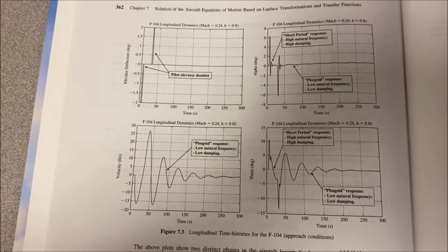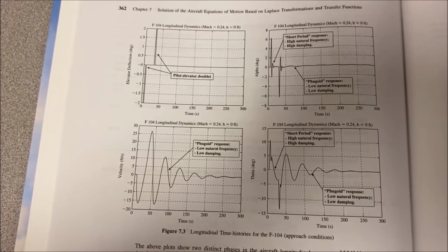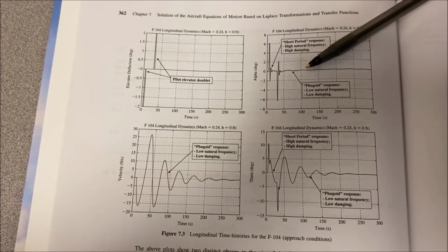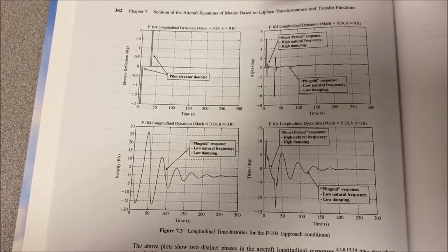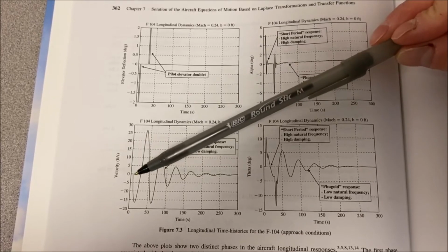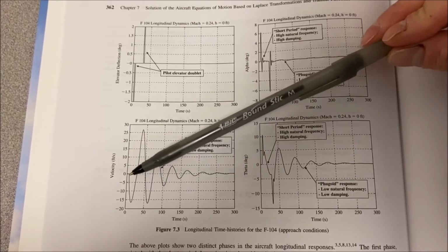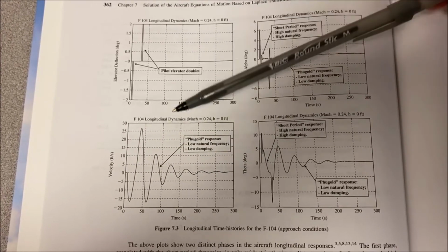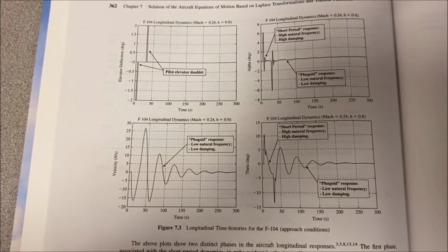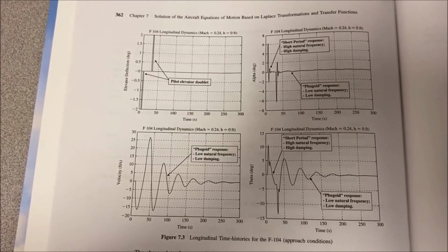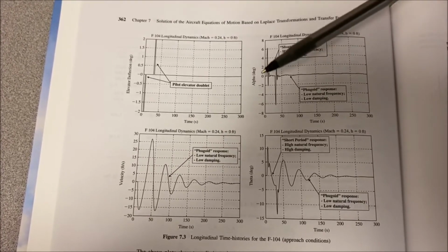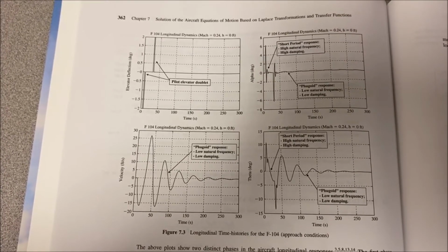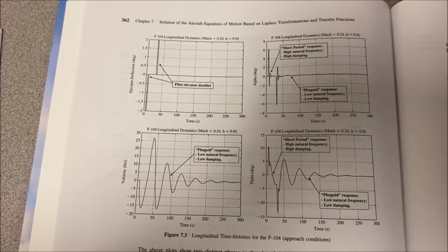And for those same inputs, we also have the phugoid response, which is the longer period pitching response there. And again, all of that is found as a function of t, in this case u as a function of t, to show how the aircraft responds to dampen out those oscillations. So in this case, both the short period pitching oscillation and the phugoid are both stable. And this is an example for the F-104, the Starfighter, right? And we will see another example of this in a moment, but for the lateral directional stability modes.